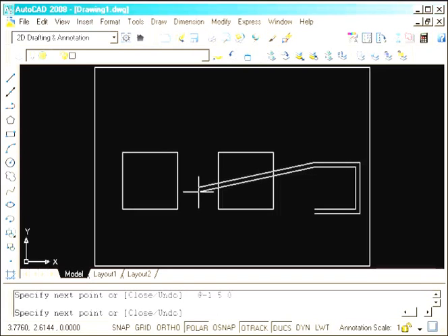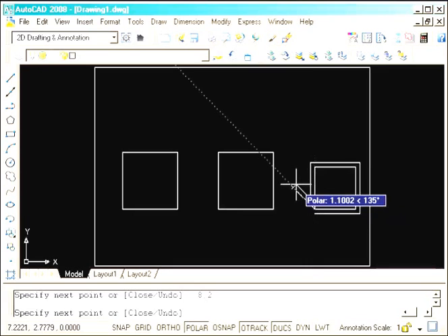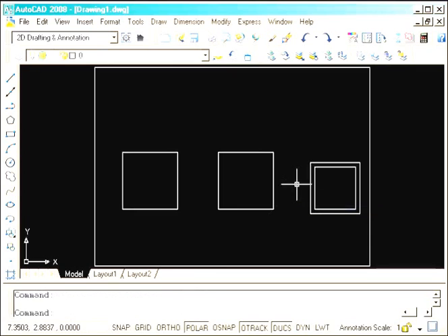And if I was to go back to my original point, you would see that it doesn't quite close in the bottom left corner, meaning the outside lines won't close. So what I want to do instead is use the close command to enter in that so that all lines get closed and it ends up looking nice and clean. But once again, that's not something you might be using. There are certain areas of drafting that will use it.